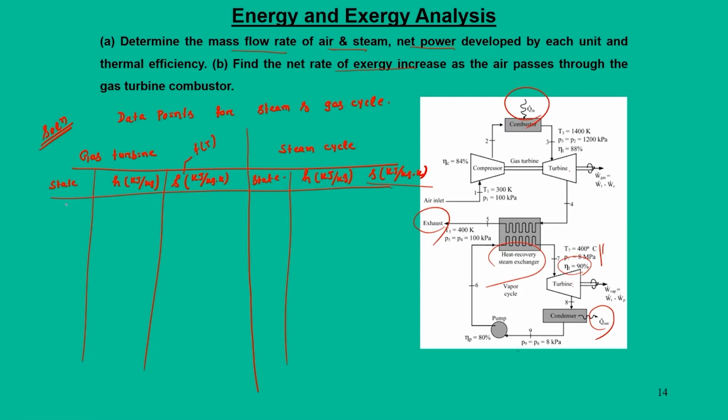Typically for gas turbine units we have 1, 2, 3, 4 and 5, and their numbers are, I am just writing down, 300.2, 1.702, state point 2, 669.8, 2.509 for entropy, 3, 1515.4 that is enthalpy, 3.362 entropy, 4, 858 and entropy is 2.762, state point 5, 401, 1.992.